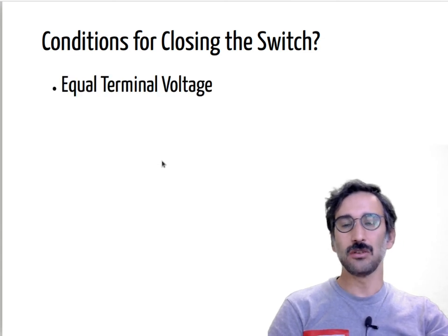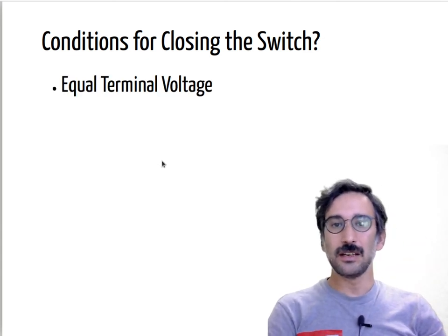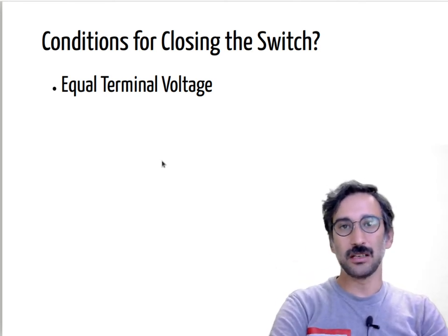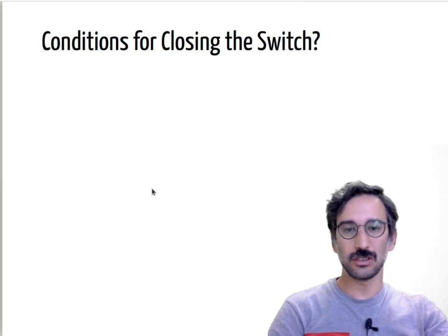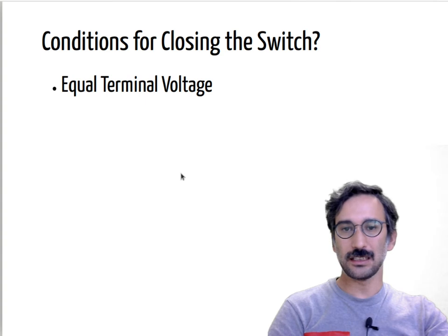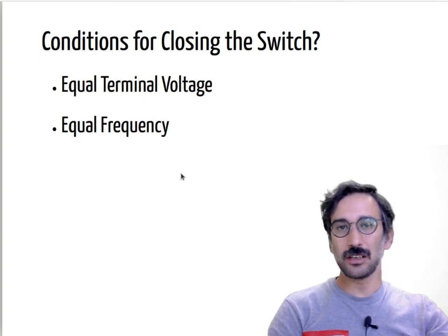First you want to make sure they have equal terminal voltage, so there shouldn't be any high inrush currents because of a voltage difference. The voltage at that side should be equal to the voltage at that side, and moreover the frequency should be the same.